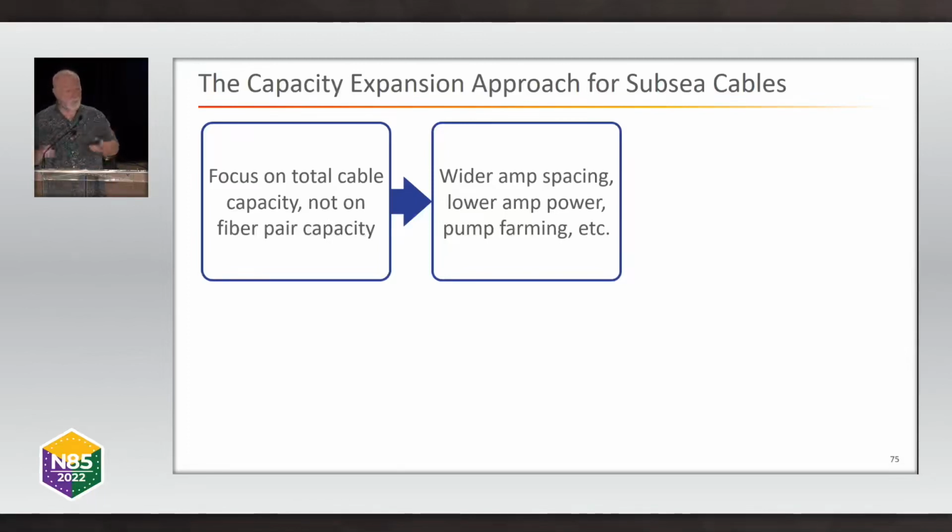do sharing of your backup pump lasers, because remember, these amplifiers in a submarine cable, they live under the ocean for 25 years. So if your amplifier pump lasers burn out, you can't lift the cable and replace the amplifier housing. That's very bad. That's very expensive. What you do, you put backup lasers in those housings. And normally it's 1-for-1 backups, which uses a lot more power.